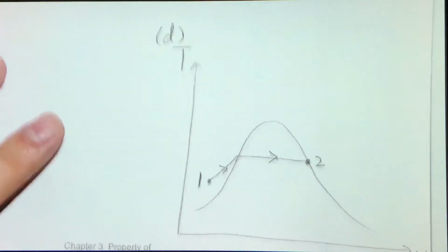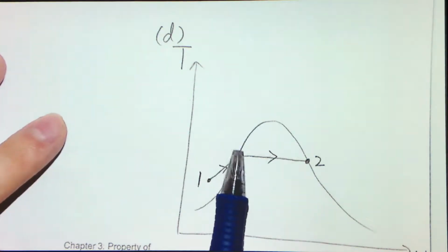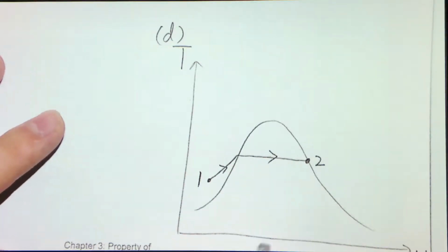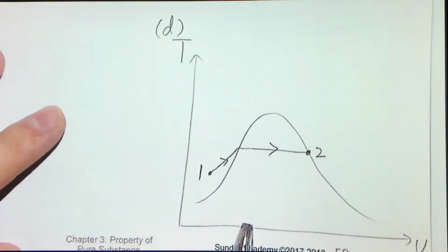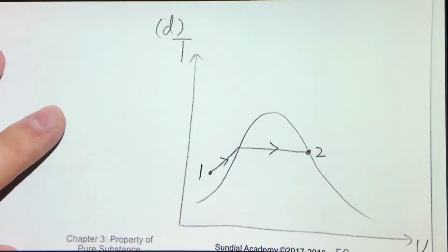So from this schematic, we know several things. First, compressed liquid, and then it will go to saturated liquid at a constant pressure, and then it just goes horizontally. So this example gives you a chance to construct a T-v diagram, and it is important, especially in later chapters. We need to rely on the schematic to solve the problems. Otherwise, you would not know what's going on.